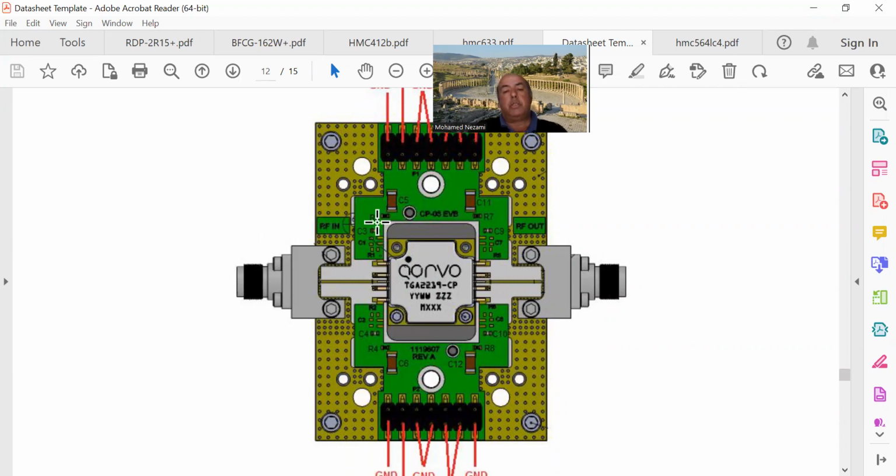the DXF file. They provide you with this on their website. You can download the layout, the PC board, the artwork. So one thing you could do is grab this and make sure you follow the exact layout, especially the thermal dissipation layout. Otherwise, the device will keep overheating and you won't get the efficiency that is claimed.